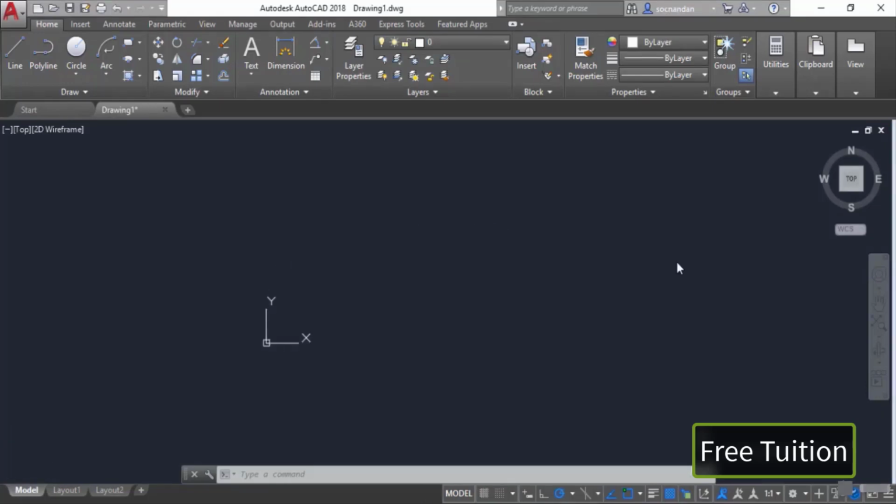In this video I'll tell you about making rectangles in AutoCAD. We've already seen the simple methods of making a rectangle using the line tool, but we have a direct method of making rectangles in AutoCAD as well, and that's using the rectangle tool. Here we have this rectangle tool on the draw panel, and when you expand the flyout you'll see the rectangle tool here. Now select the rectangle tool, and now you need to specify the first point for making the rectangle,